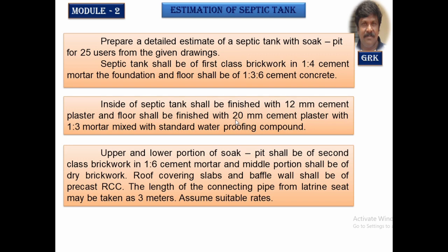The upper portion of the soak pit is of second class brickwork with cement mortar 1:6, and the middle portion is of dry brickwork.